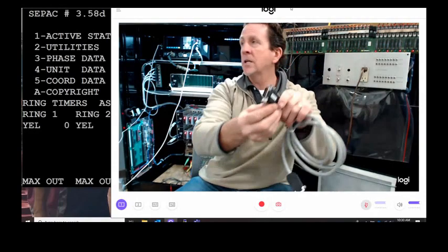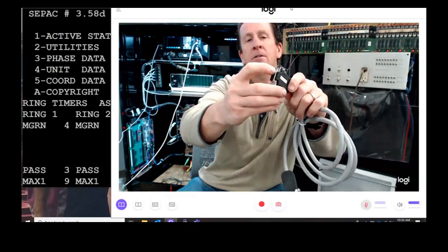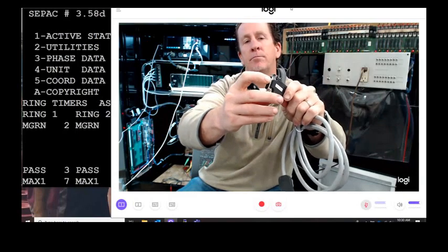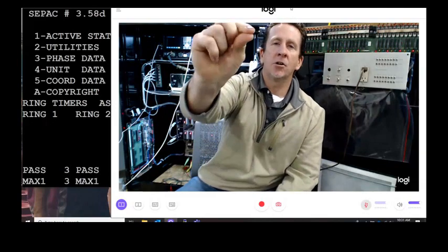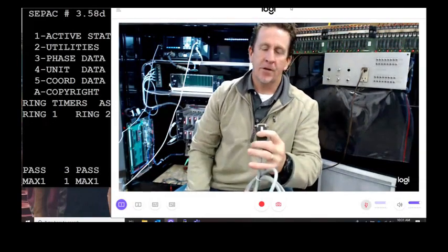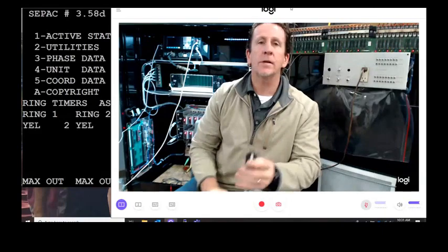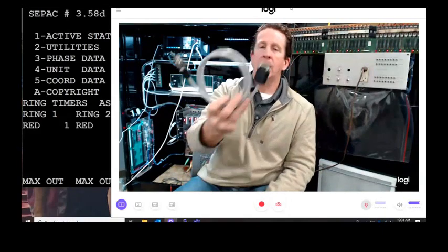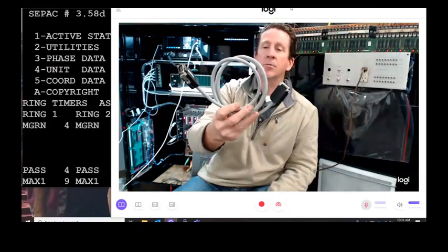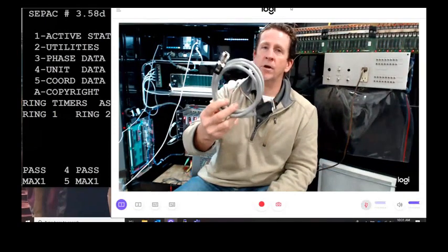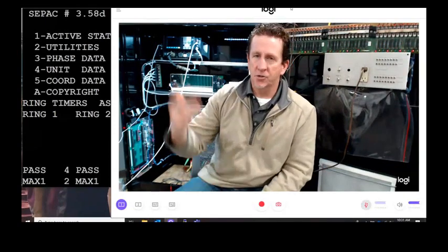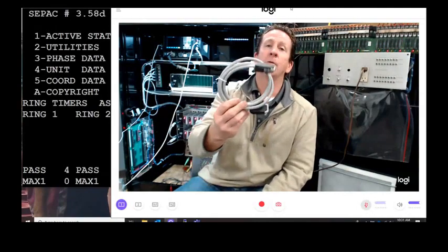What I like to do is push my finger down on it with about a half pound of pressure, and those pins should all stay. I should see all the pin marks in my finger. If one happens to go down or if one's broken, that's going to give us our problem. And like I said, they're easy to replace. If you can glom one or two BIU cables from somewhere out of a cabinet that was destroyed in a knockdown or something, it's good to have a couple of these on the truck as well.